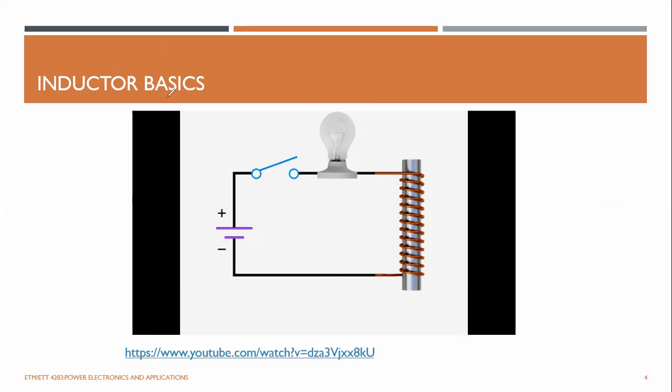You may have seen how this works. When you turn off an inductive circuit, the inductor was carrying some current. If you just remove this connection, the inductor current does not change instantaneously, which means it needs a path. That's why it provides some arc in here.